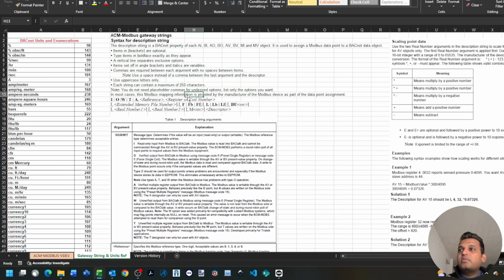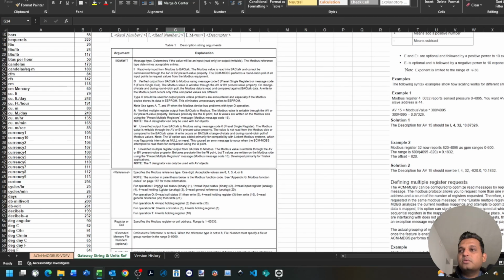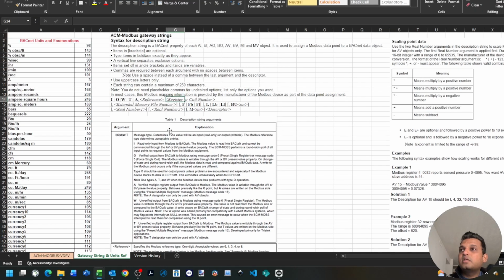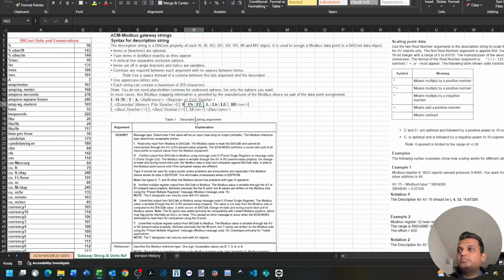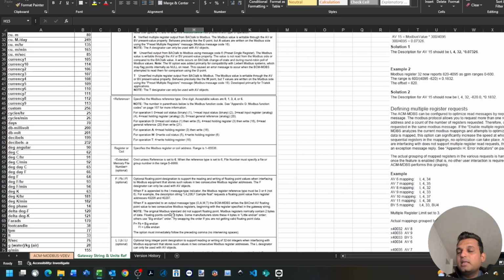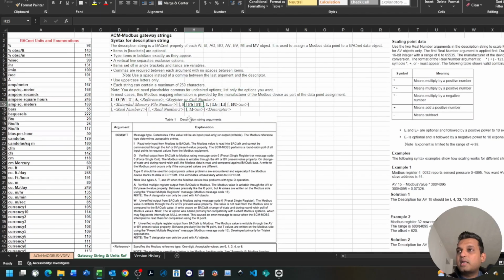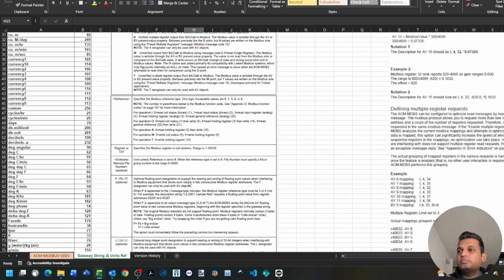So then you have register or coil number. So okay, I am reading 3000, which is my current A for my energy meter. Then what is the extended memory? I do not have an extended memory, so I will skip. Then I will define floating, because my points are floating points, so I will say F. Then again, in floating points there are different variations.